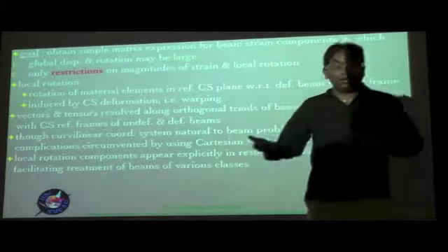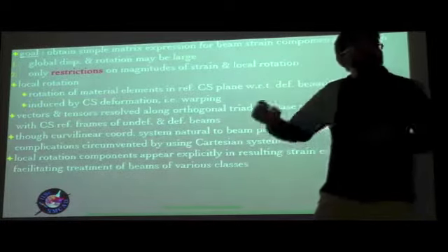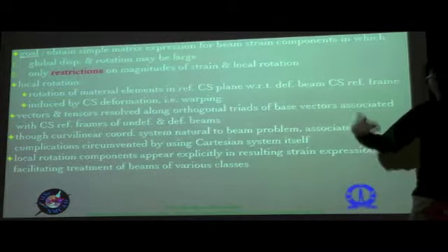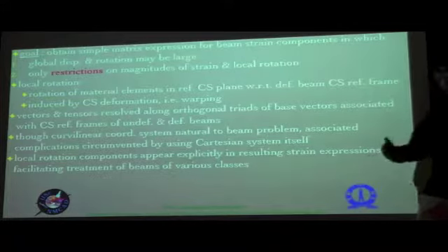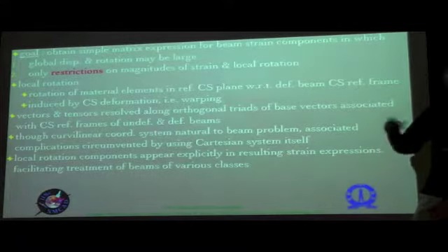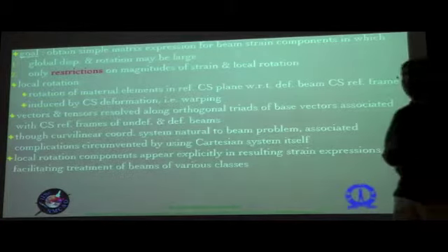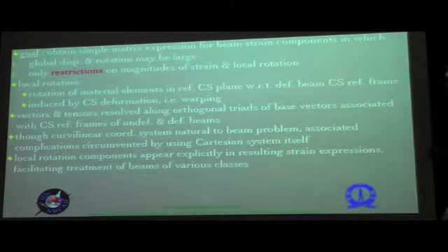If they are not small in the case of R-class beams, it so happens that the strains that result will be large, and therefore from the fact that the strains are small, we argue back to show that they are small in the case of R-class beams, whereas they can be large in the case of S-class and T-class beams.